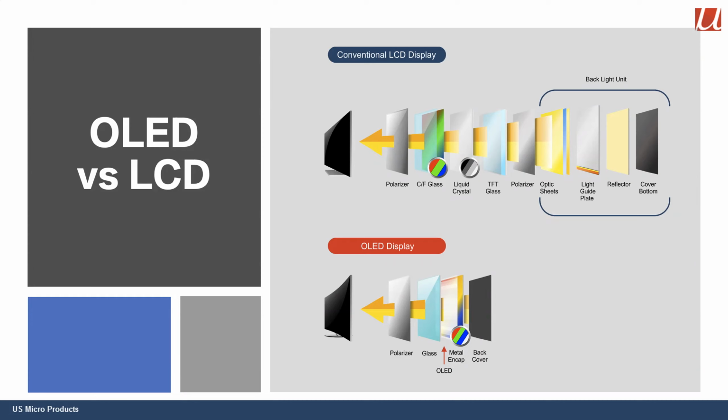The majority of the magic is in the OLED array itself, and that's built in that very expensive factory using those very expensive masks laid down on glass, usually with one polarizer and a back cover. So it's a pretty simple mechanical structure. It can be very thin and very light, which is great for portable equipment. But customizing it and building it in those very expensive factories means it's relatively more expensive on a per display basis.